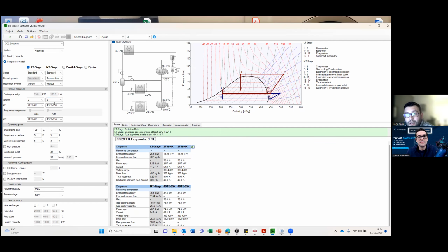And you know, the further you reduce your gas cooler output, as in the lower the ambient condition, the more compressor capacity each body will have. So you basically continue to face this issue of finding it hard to load match when you don't have an inverter. Yeah, I don't think I've seen a CO2 system myself right now without some sort of capacity control on it. Any CO2 system, mostly inverters, some digital or suction capacity control, but I think pretty much most of them will have some. They will all have, that I've seen, some sort of capacity control, mostly drives on it.